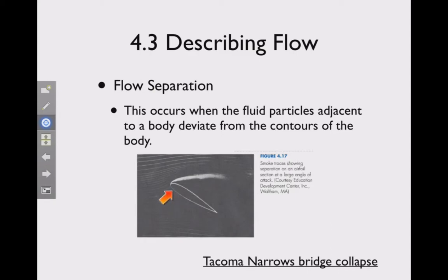We actually have the fluid in contact right at the nose of this airfoil, and flow separation is occurring right here. You can see that because it is angled at such a steep angle, we have only a very small region where the fluid is in contact with the airfoil, and then there's a large wake region behind it here.